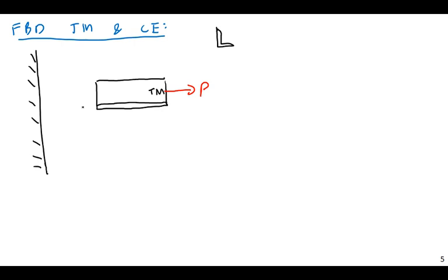However, I could just butt this right up against the column and weld it directly, but that would be a very concentrated point load in the column. The column itself may be very beefy, but it might not have the flange thickness necessary to carry that large point load. So instead, I might use a connecting element. Maybe I have a connecting plate. My connecting plate might look something kind of like that. Just a plate.